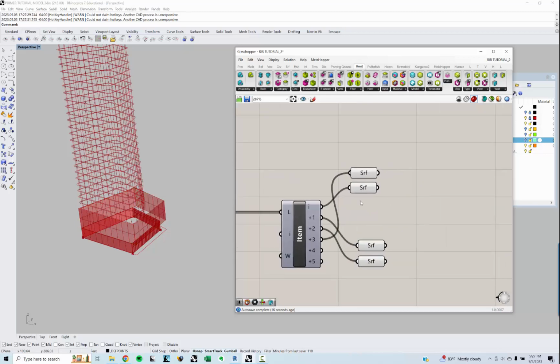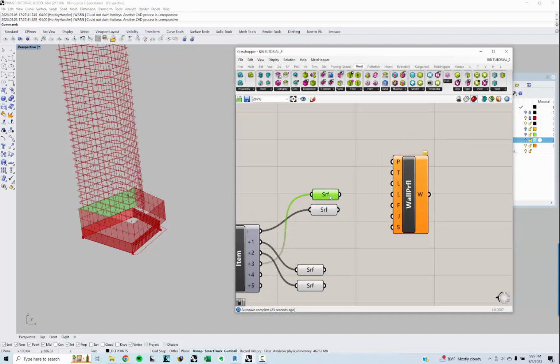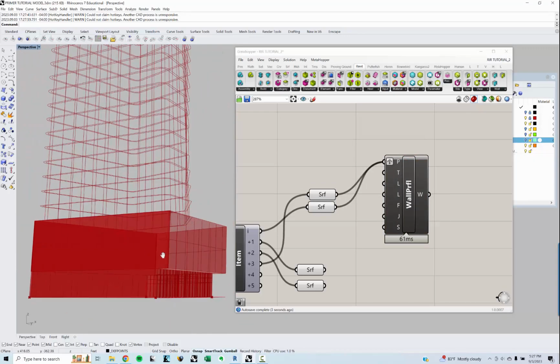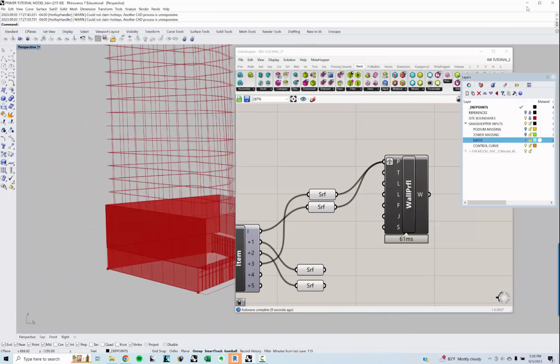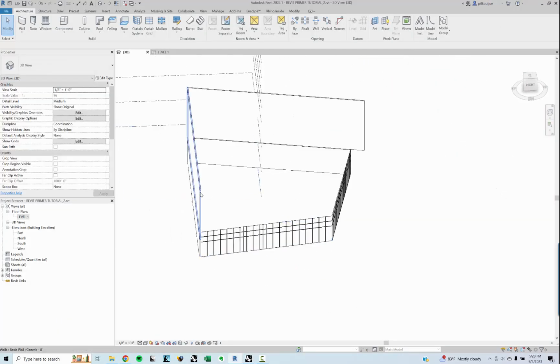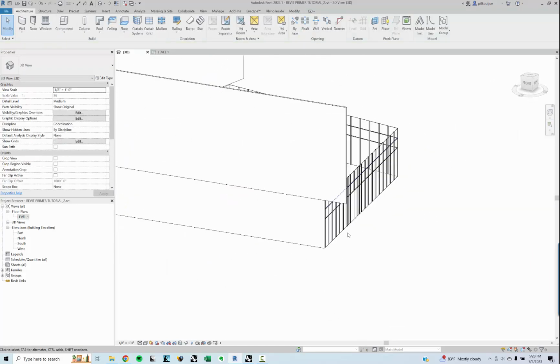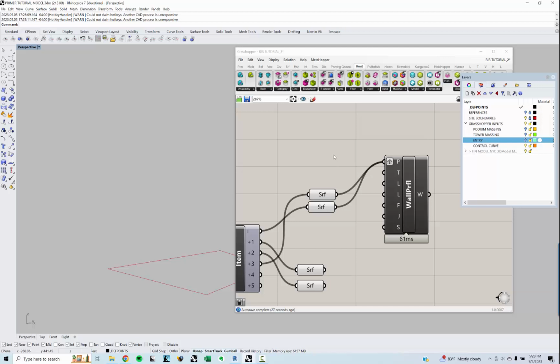The party wall is going to be straightforward, but I just wanted to show you that you can use a wall from profile, Add Wall Profile, instead of using a curve. So what it's going to get is the outer bounds of it. And so we just have these, I might need to graft these as they go in. Yeah, so I'm just going to graft them. So this is basically giving me a native basic wall here, but it's using a profile curve rather than a curve that indicates some sort of location on the wall.